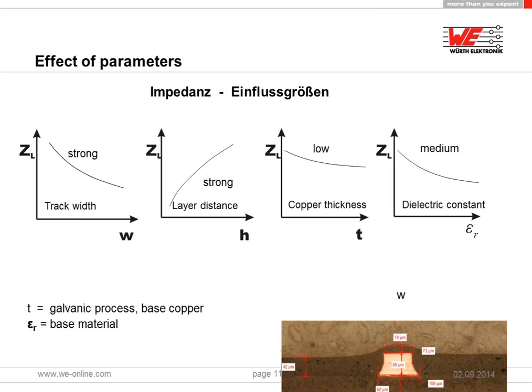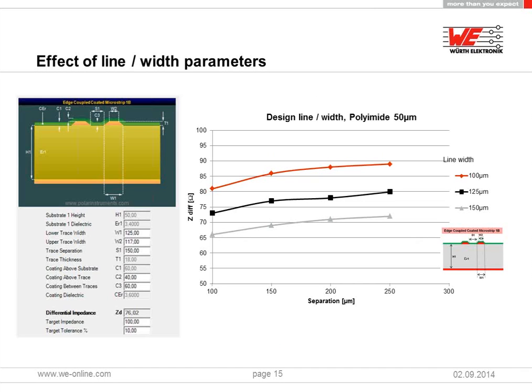So there's no real chance to get a higher impedance value even with a very fine line width. So the question at that point is, do we really need thicker polyimide to match higher impedance values? And now we come back to the reference layer, the hedge option.